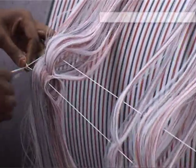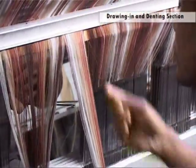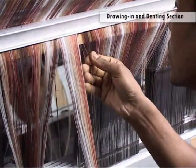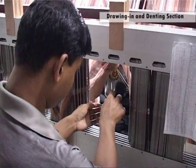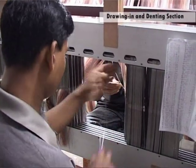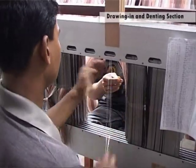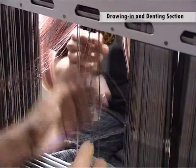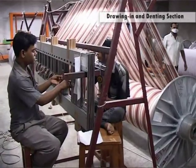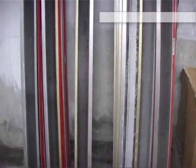Changing style means producing a new fabric style. Weaver's beam changing means going on weaving the same fabric style, just replacing the empty beam with a full beam of same type. Drawing in consists of threading the warp ends through the drop wires, the heddles and the reed. Depending on the styles of the produced fabrics and on the company's size, this operation can be carried out manually by drawing-in male or female workers.